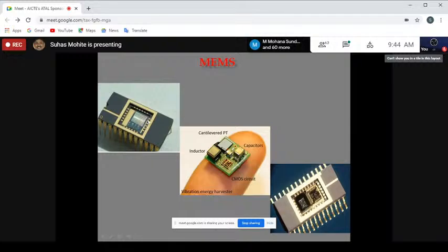Although the signal that is available is pretty small, there is amplification that takes place in the immediate vicinity alongside the electronics. So in MEMS, there is a strong integration of mechanical and electronic devices, and you can see several miniature devices fabricated on it. Electronics people are familiar with CMOS circuits. They know that there are several capacitances that come into the picture, and there are deliberately manufactured parallel plate capacitances or comb fingers that can be built using this silicon fabrication technology. Even inductors can possibly be created. A simple cantilever beam or diaphragms can be fabricated on this silicon substrate, and various transducers can be realized.